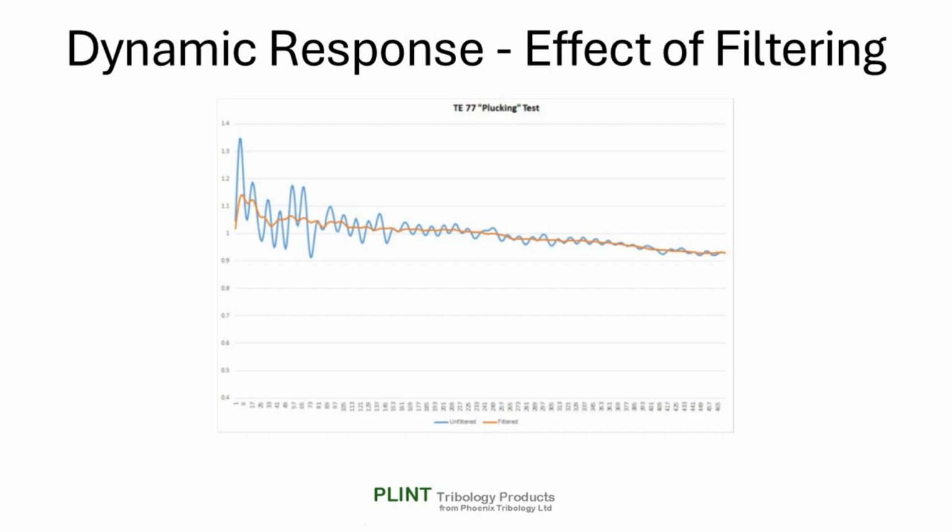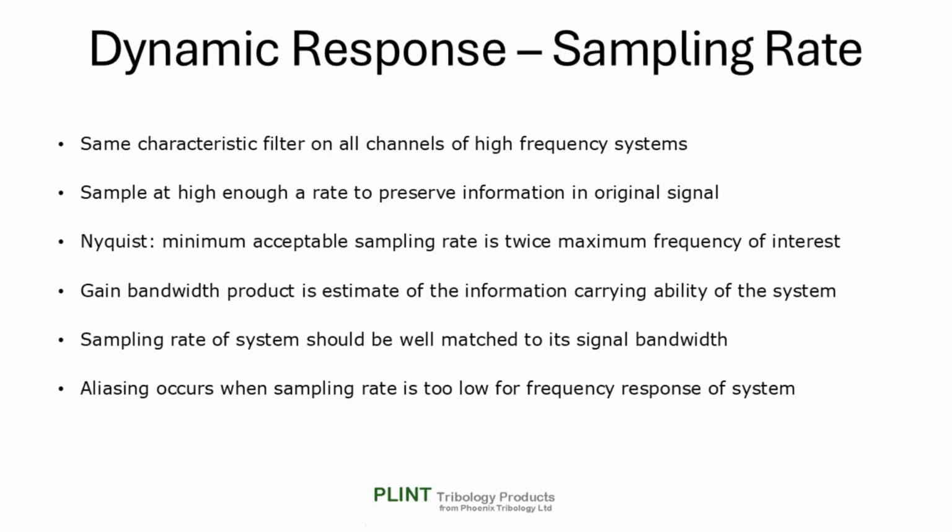We can tidy up a signal by applying filtering. This effectively limits the signal bandwidth of the measuring system, removing the higher frequency components we wish to hide. Having discussed the response of our force transducers and how we might clean up the signal, it is probably worth mentioning something about sampling rate and the possibility of aliasing.